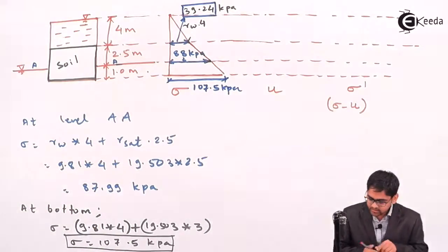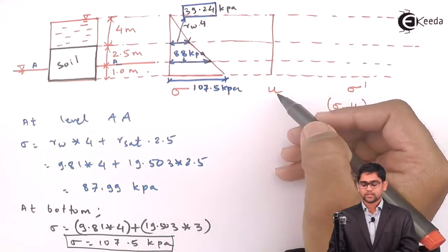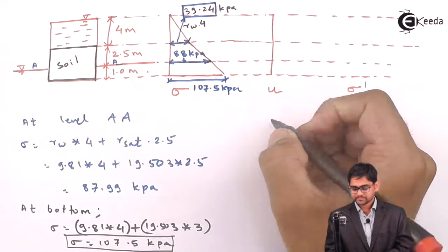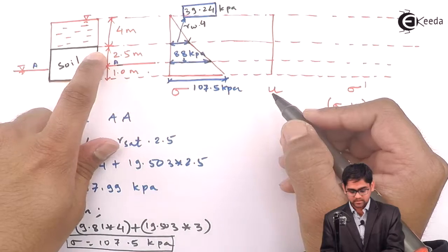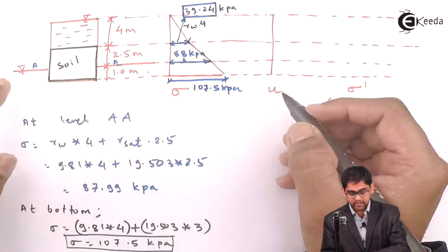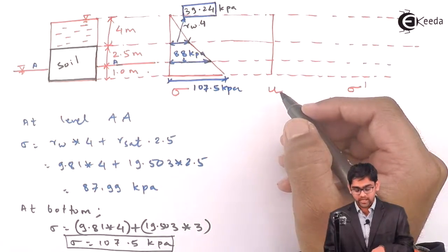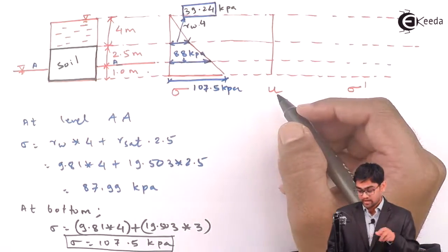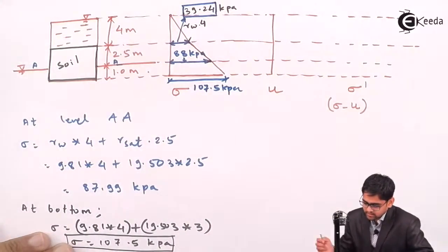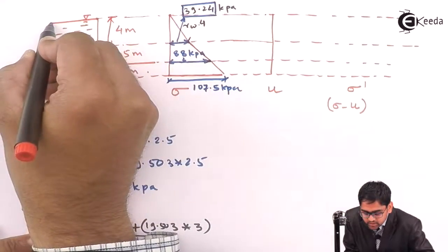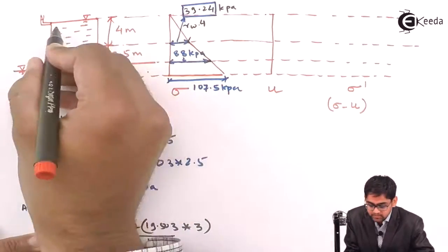Remember, it is not easy to calculate. So in order to calculate it, you need to place a piezometer inside the soil sample, and you need to measure the water level to which the water has risen in this piezometer. So the U for this particular case is, if you insert the piezometer over here, you will not get any rise in the water level except capillary.